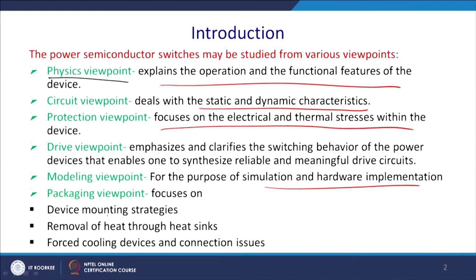And then packaging, which comes under different kinds of packaging, because we want the devices to be compact. It may come in ceramic packaging or plastic packaging depending on thermal runaway, different kinds of cooling systems and compactness. So, it comes to device mounting strategies, heat sinks and how you will dissipate the heat in different ways, forced cooling and the connection issues.